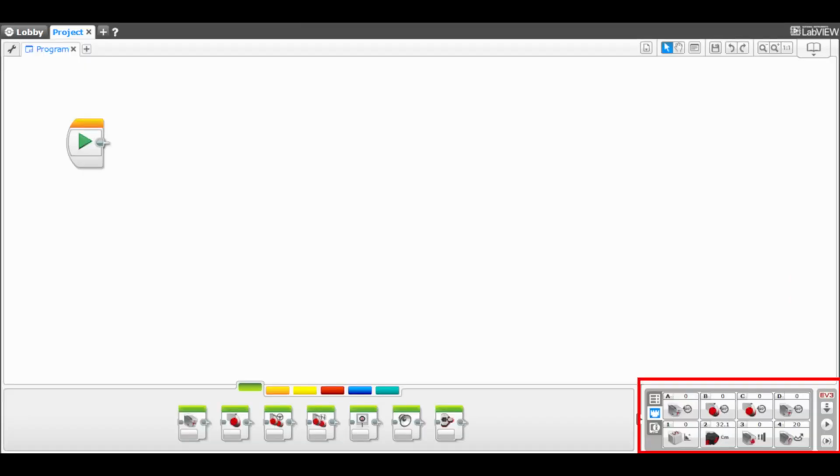If you have an EV3 Brick, you can also connect it to your computer using Bluetooth, Wi-Fi, or using the included USB cable. This allows you to do many things such as update the firmware of the brick, browse the files stored on the brick, and upload projects and programs remotely to the brick. The LEGO Mindstorm software also allows you to view which ports the motors and sensors are plugged into so that you can correctly reference them in your code.